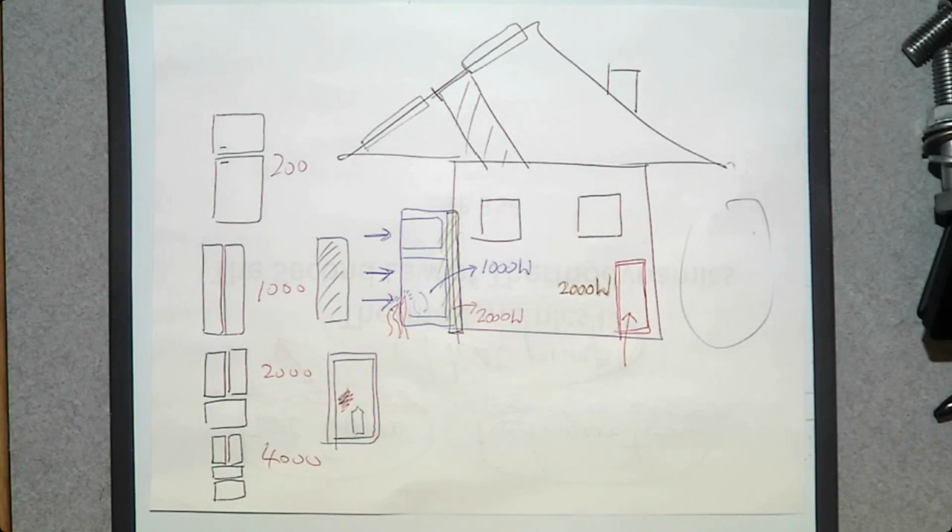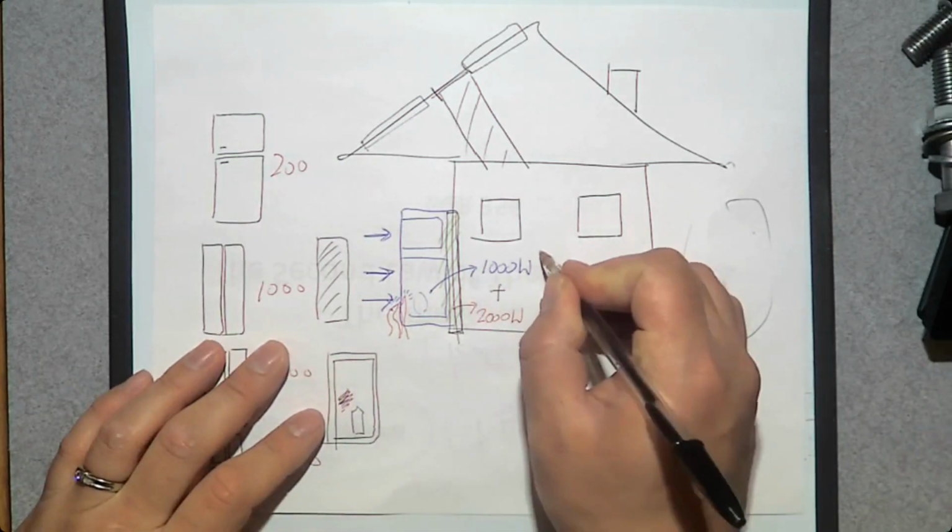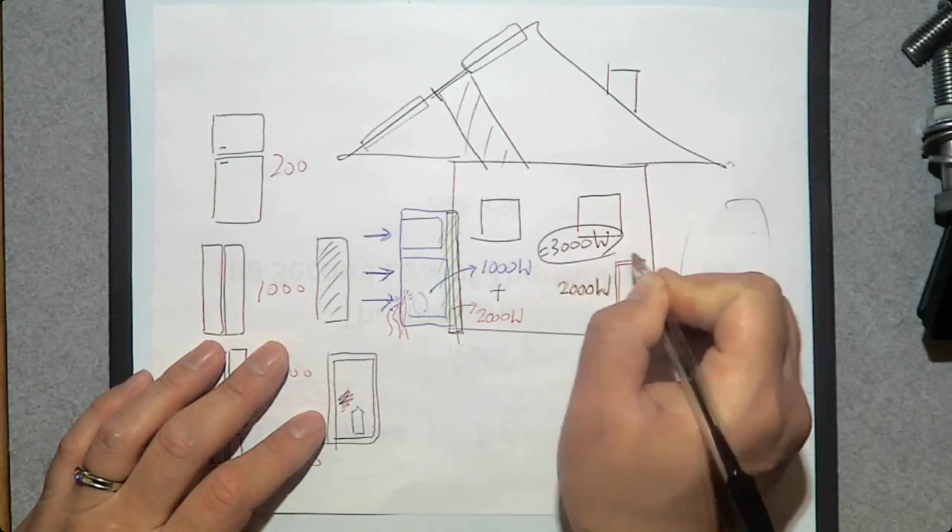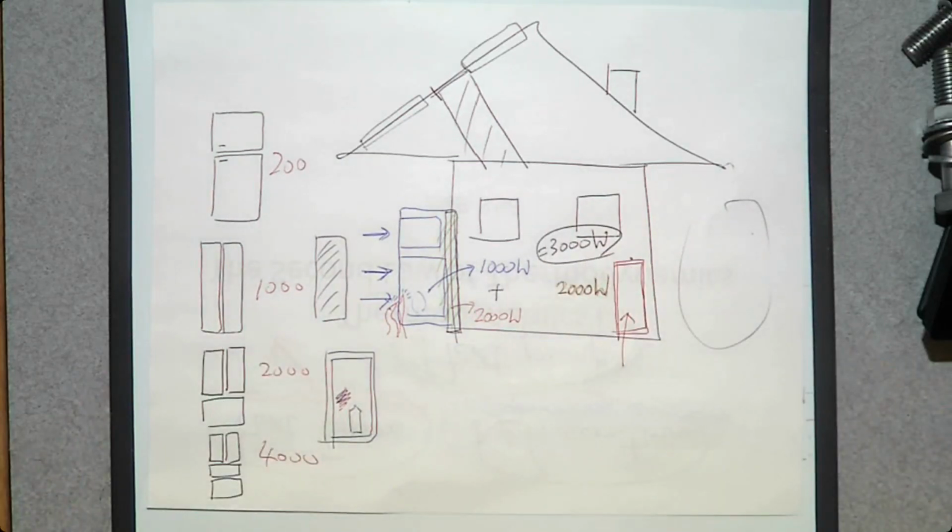Now, you spend 2,000 watts. And what is the final form of energy? What is the final form of energy? Heat. So this 2,000 watts becomes what? Heat. And then you are removing heat from the food, but there is no food, so from the air outside. And that heat is going to be pumped into the house. So you spend 2,000 watts. And how much heat do you get? 1,000 plus 2,000, 3,000 watts of heat goes into the house. Make sense? That's how a heat pump works.